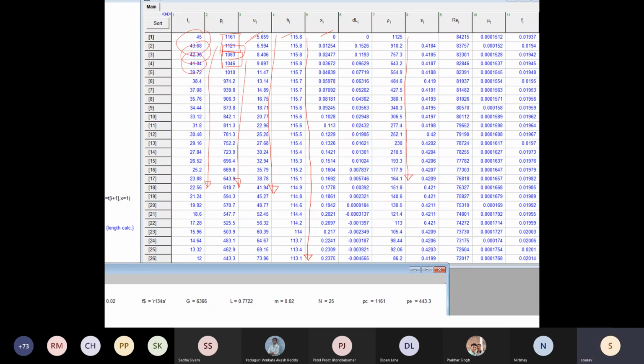Okay, so across the capillary tube, the specific enthalpy is not constant. It is the summation of specific enthalpy and specific kinetic energy which is constant. And you see the gradual change in the quality. The quality keeps on increasing because you will have more and more vapor.